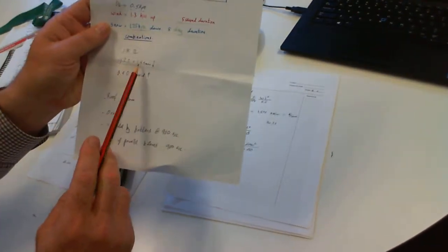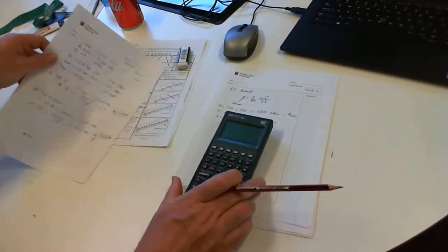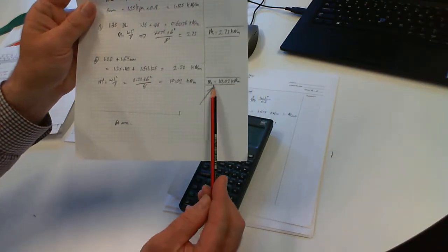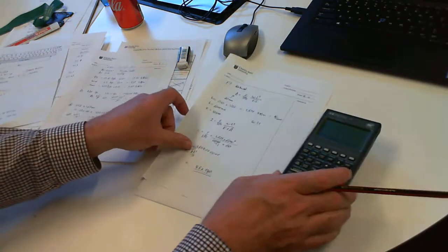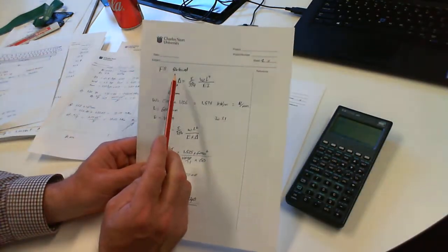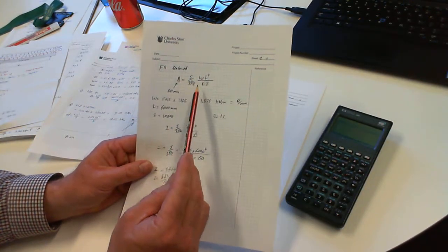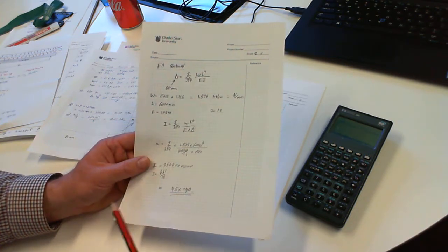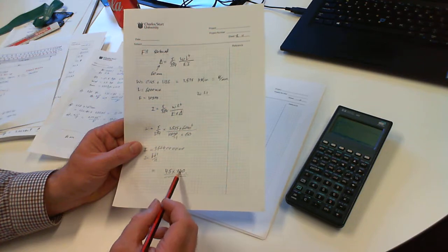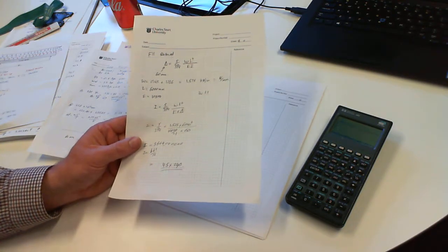1.2 times the dead, and 1.5 times the snow load. And we found that that second one is the limit state that we're going to find for. That's the strength limit state. We have picked an F11 seasoned timber beam, and we've worked out a basic size on that based on a 60 millimeter deflection. And so we've ended up with 45 by 240 size beam.